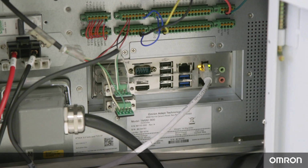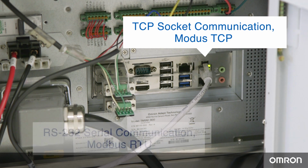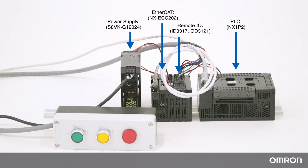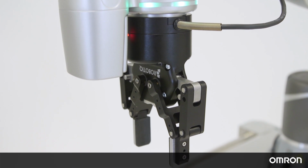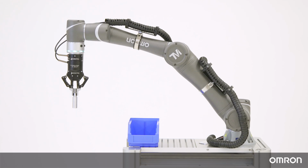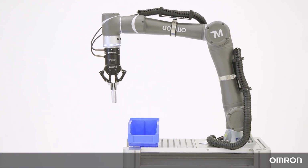The TM Cobot is capable of different types of communication: TCP socket communication, RS-232 serial communication, ModBus TCP, and ModBus RTU. Each of these communication protocols allows the TM Cobot to communicate with many external devices, such as OMRON NJ or NX PLCs, robotic grippers, and shop floor communication systems. For the rest of this video, we will focus on using ModBus TCP communication in TM Flow.